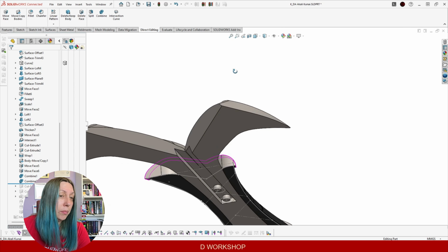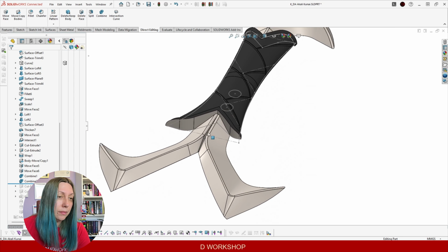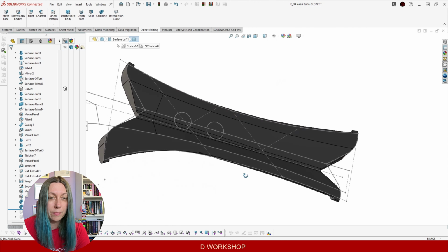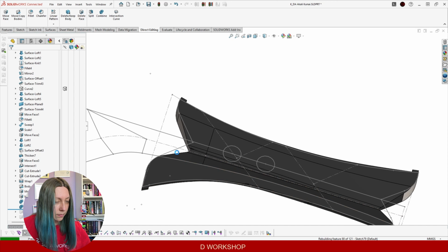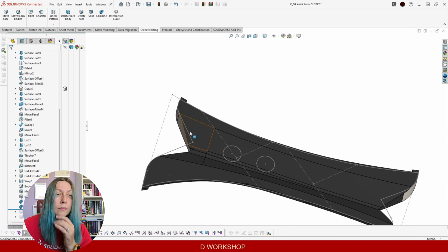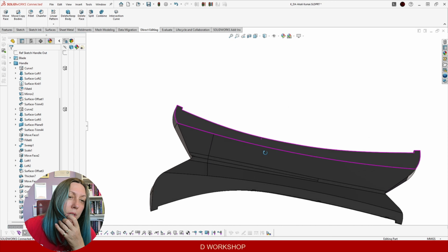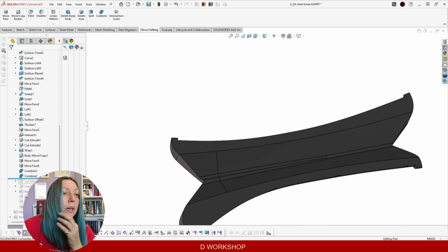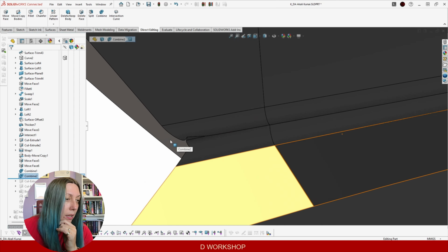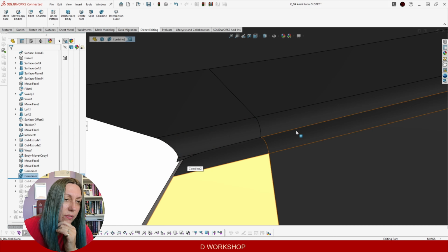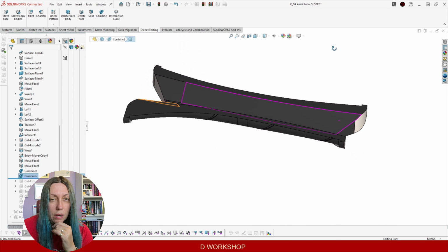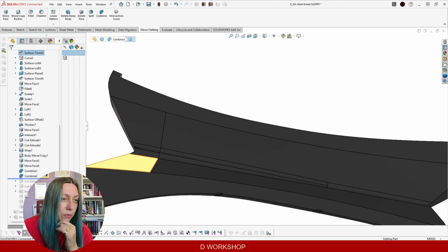And I will use another combine to cut out the inner handle from the outer handle. Now let's see when I hide it what I did. I will have also this sketch. Now I have a perfect fit. But in life nothing is perfect, so we will move this face a bit later, because at this point this very sharp edge here will make us a problem. I should finish my edits to the outer handle before I put the offset.